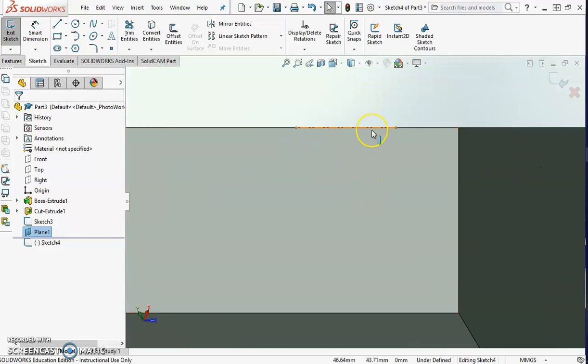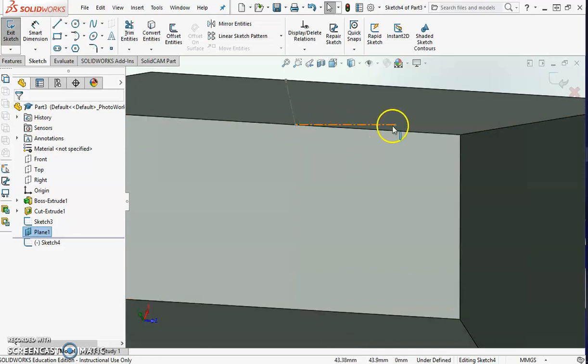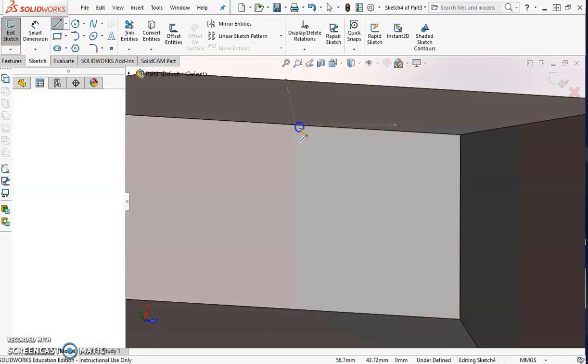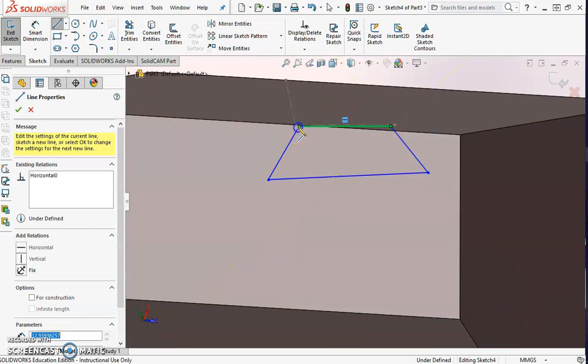So it's still on a strange view because we're cutting at a very, very strange angle, but you can see the two little gray dots here, and if you rotate just slightly, you can see the construction line that we drew. I'm going to use my line tool, and I'm going to draw a trapezoid. And it's not going to connect to anything right now, so just draw your trapezoid in, something like this, and afterwards we will fix that thing up.